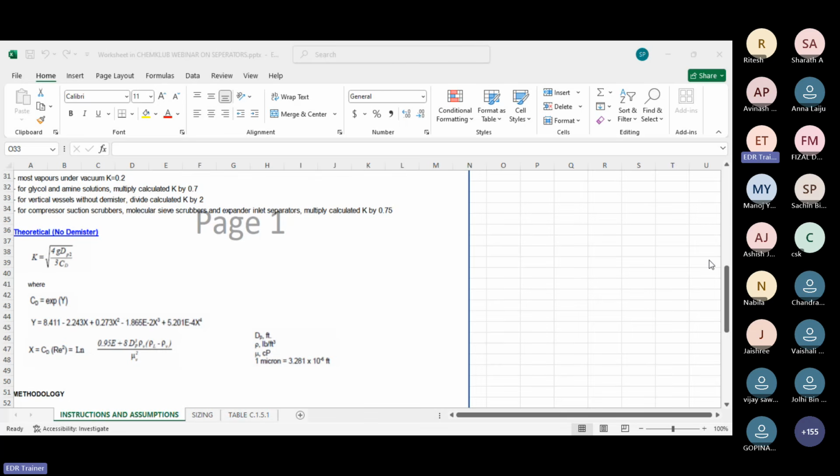Gas, liquid, liquid. So in the oil, water is only 2 to 3%. If you have 2 to 3% and the quantity is too small, at that time we are going to use a boot. Okay, that will help to collect it from the system, because a boot is required when the second liquid component flow is too low.